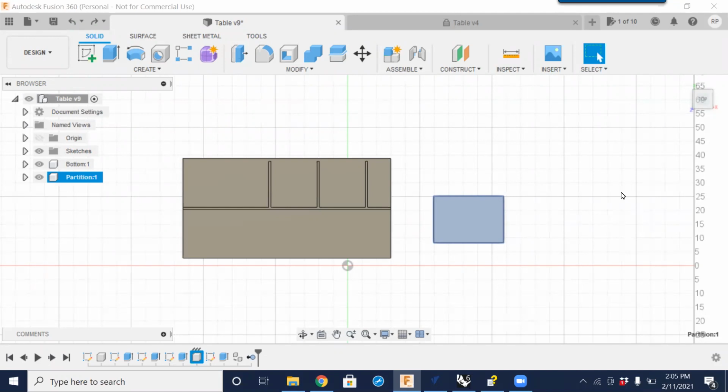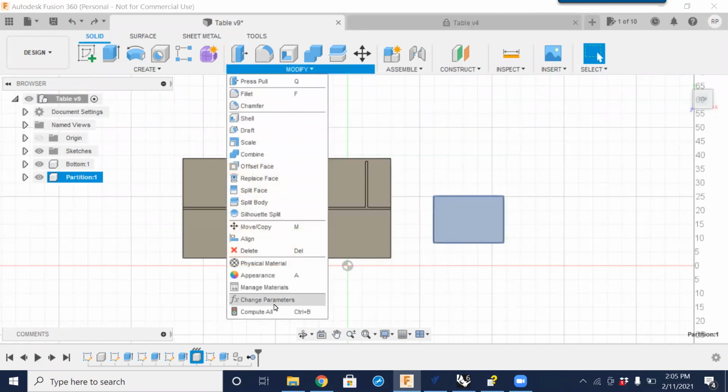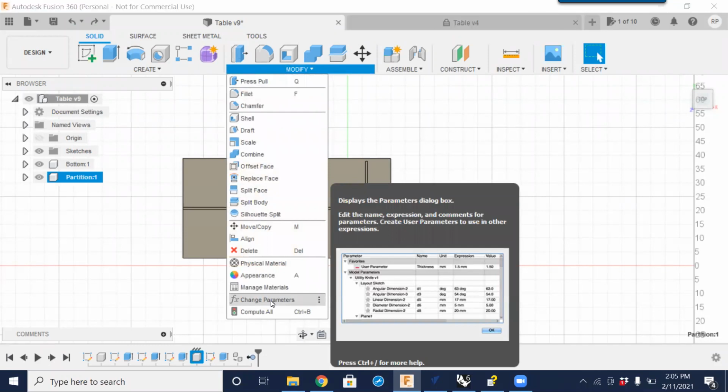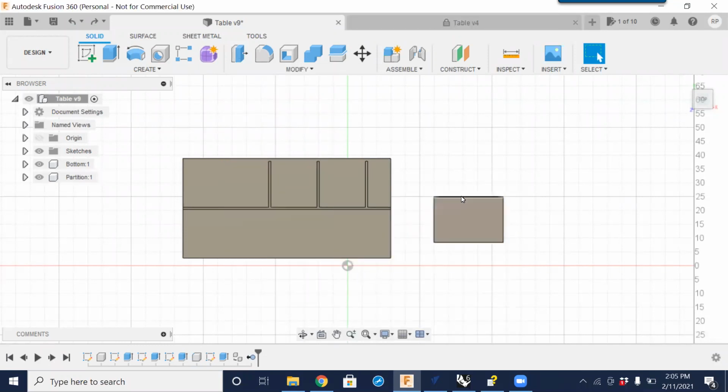Now, we learned last week about constraints within a sketch and within the heights of the model, using the modifying of the configuration parameters. We will get into that in a bit. But the constraints that we have from one component to another, they call joints, or being able to assemble. The first thing that we need to do in creating an assembly is ground one object or one component that we do not want to move around.